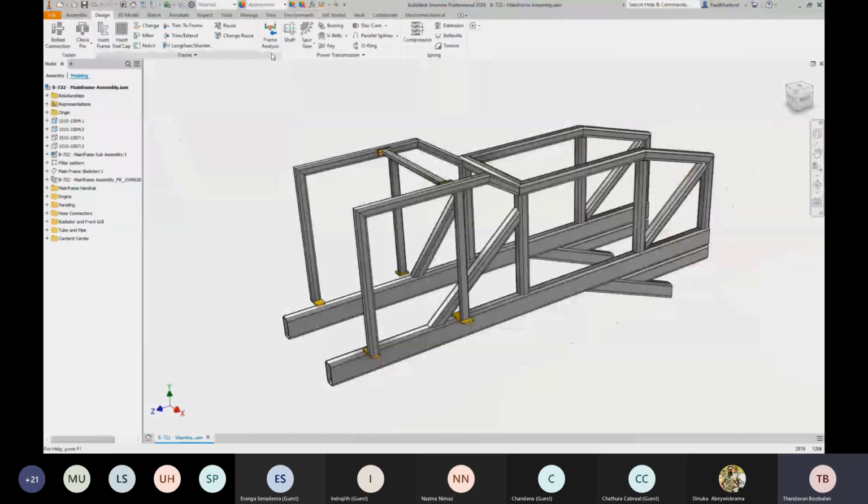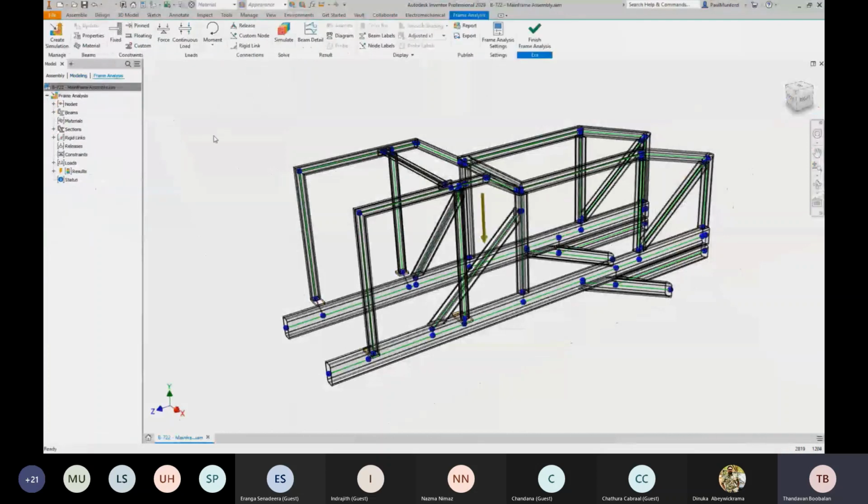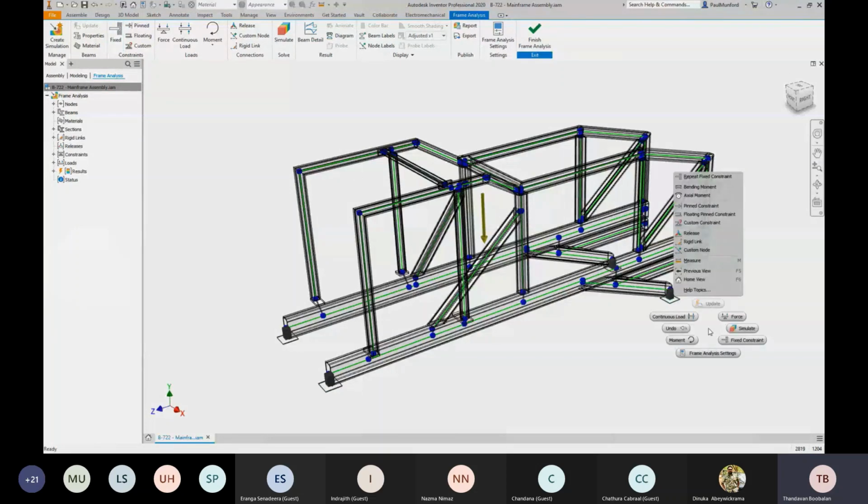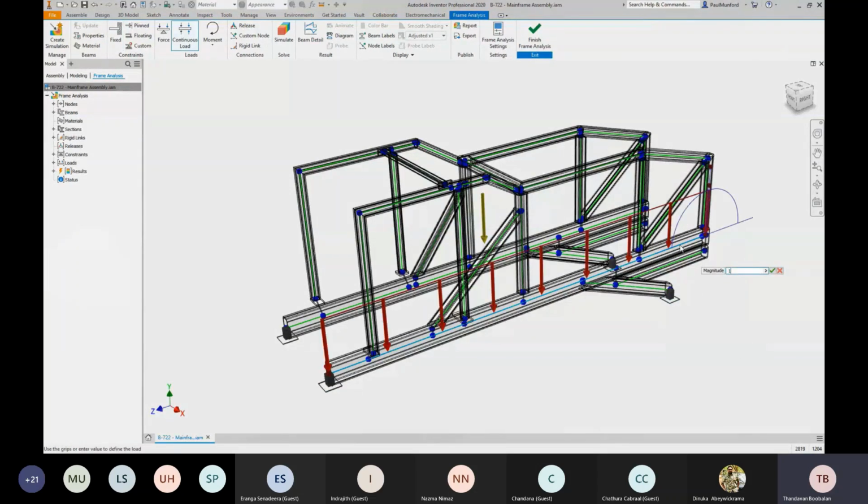The standardized nature of frame design also makes it easy to set up and perform structural analysis to make sure your design performs as required. Just add your constraints, for example where the frame is fixed to the floor, and you can start specifying where the loads will be applied. Loads could be applied as point forces, axial moments, or continuous loads across the length of the frame members.